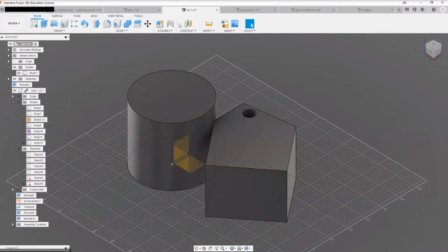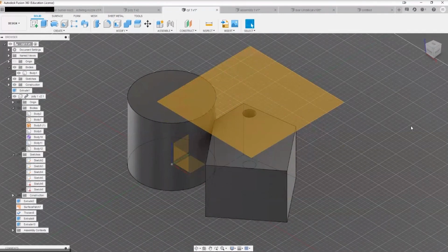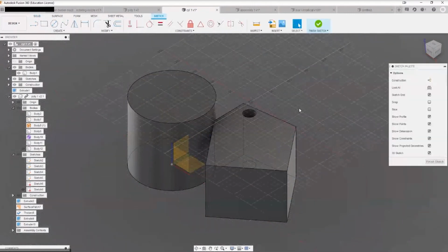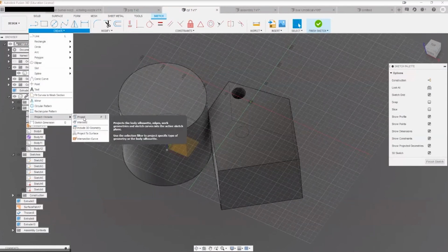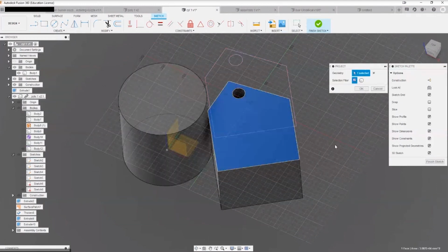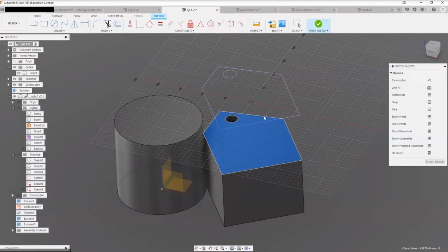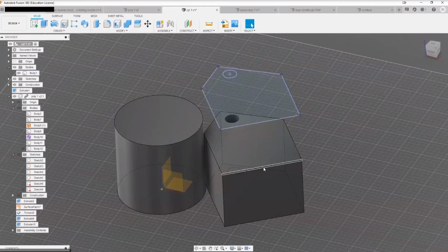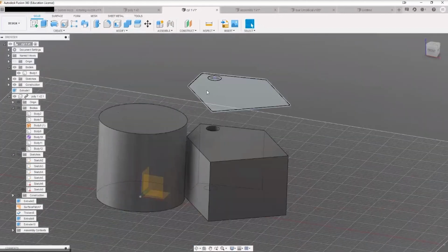So if you want to create a DXF file off this, best practice would be to create a construction plane off that, create a sketch, and actually this is a really important trick that I'm going to show you. Don't forget to try these projection tools. Just select the surface, and it's going to import this geometry directly into the new sketch. It's almost like copy pasting it without having to go Control-C, Control-V through it, because things might shift. So this gives you direct representation.